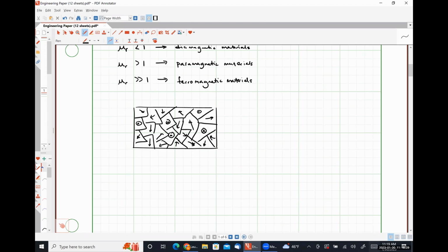It's definitely related to the grain structures because that's what all of this is about. But I don't know. Well, I'm just thinking if you're talking about nails and rods, drawn out segments of metal, having to work it out into a shape, then cool it, heat it, cool it, heat it. You are moving the grain boundaries, but then you're also introducing, what am I trying to say? As you're heating it and stretching it out, in addition to moving around the grain boundaries physically, you're also causing diffusion of materials.